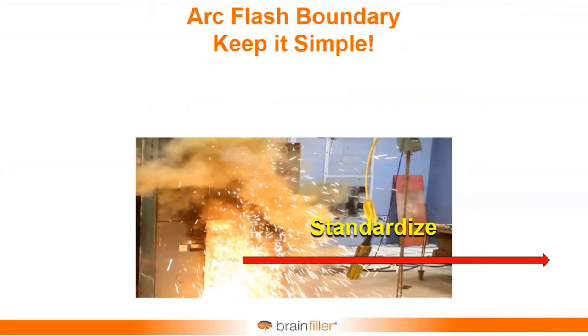And I actually first introduced this concept back around 2004. It was at a conference that I was speaking at. And I mentioned, just select 8 or 10 feet or something large. And a few people looked at me like, well, isn't that kind of extreme? And I said, well, it really only affects the person that doesn't belong there. So just get them out of the way. And it does maybe affect where you're going to put on your PPE once you're getting into the area. But as I said, once you open the doors and you have the arc flash hazard, you're doing that anyway.